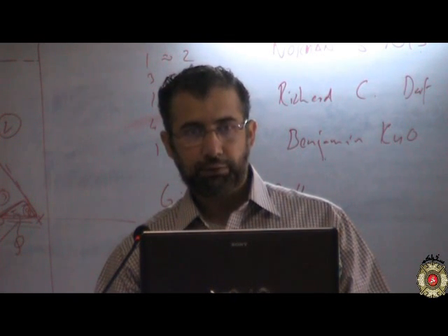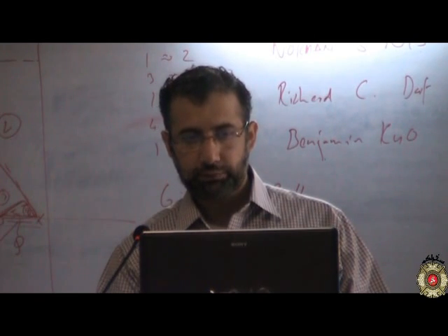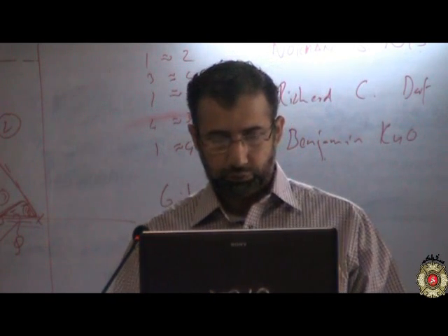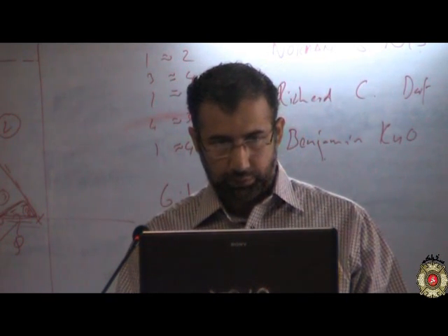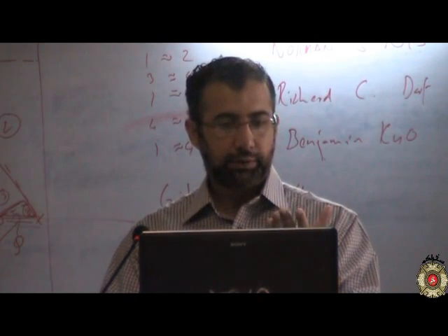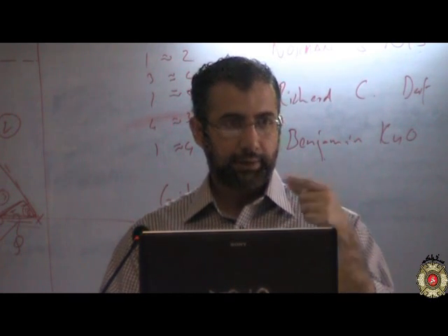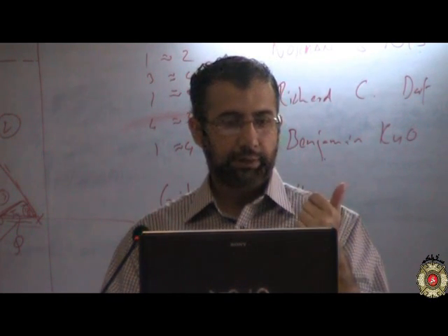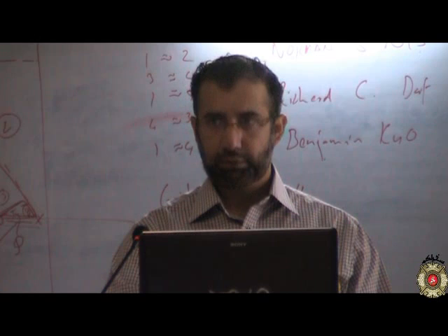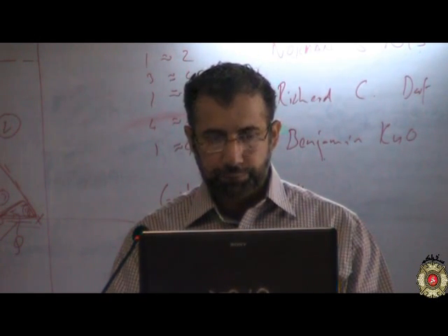So now we said the forces are because of two things. One is the weight, the other is the pressure. This weight is already there. Now let's do it for the pressure. Let me ask you this. I wrote weight and then I wrote delta W of S. For this small particle, this is the weight acting in the S direction. For pressure, can I write delta P sub S? Why is that? Right, pressure is scalar. So that is why I wrote F of P sub S.